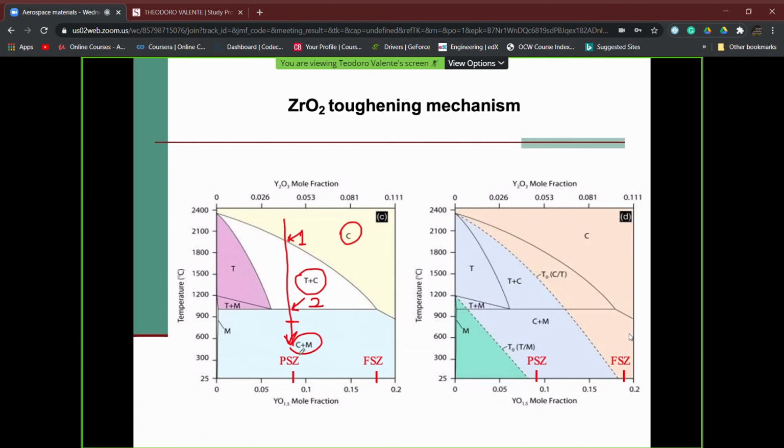So this means that the tetragonal, if we have in mind a cooling process, which was present in this area of the diagram, more or less has been transformed in monoclinic. Still, the cubic exists in the form of cubic. This cubic zirconia, which is stable at room temperature, still remains cubic when we go here, still remains cubic when we go at temperature values higher than the value T1, this one.